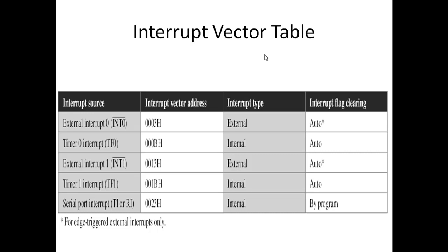Keep that in mind. Whenever a microcontroller is providing service to an interrupt, it needs to perform certain tasks which a peripheral is demanding or anything else that is generating the interrupt. For example, I was saying the interrupt is being generated at INT0. As soon as the interrupt occurs, the microcontroller will suspend the execution of the current program and go to the vector address of the corresponding interrupt.